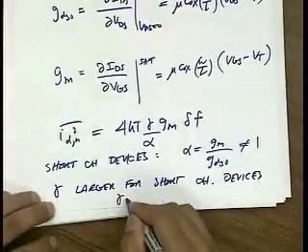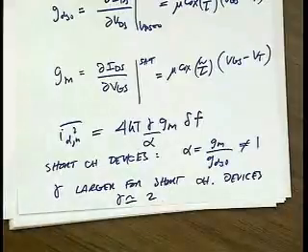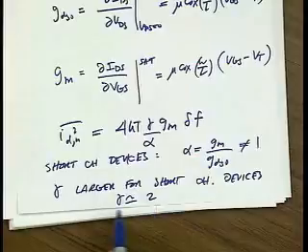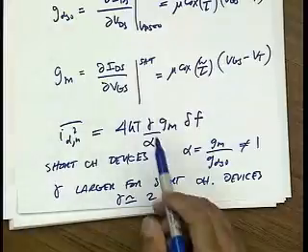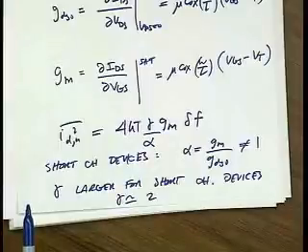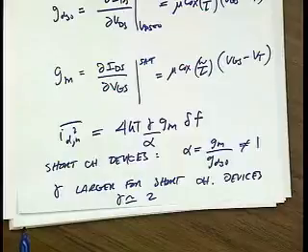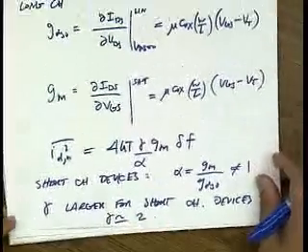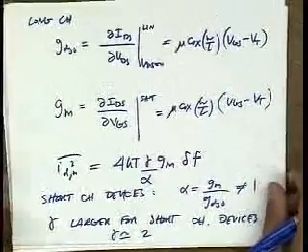Okay, so gamma maybe on the order of 2 is reasonable for a short channel device. And it depends on bias, it depends on how short the channel is. The important point to take away is that you should treat gamma as a parameter that you get from the process. And don't treat it like 2/3. Treat it as some value that you need to find out when you're doing your design that's going to be larger than 1. Okay? Any questions about the thermal noise of the channel?